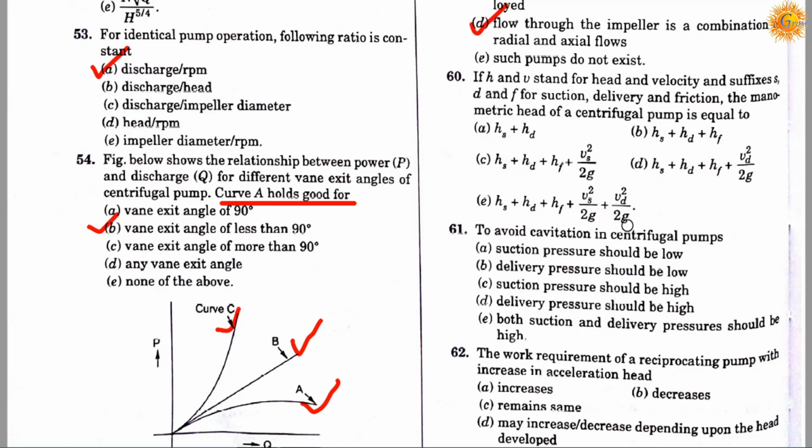So correct answer is B, it will be hs plus hd plus hf, the suction, delivery and friction heads, the manometric head of centrifugal pump.